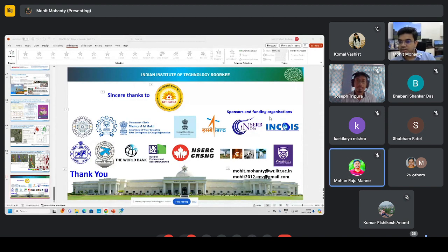Thank you, sir. There's another question by Divyashni Pandey: what are the different calibration parameters for urban flooding? For urban flooding, or for riverine flooding also, the first parameter is the Manning's roughness. Whenever we create an urban flood model setup, we also have to create a network of the man-made drainage systems, so we have to take care of what the optimum Manning's roughness coefficient should be. Similarly, for a riverine catchment, the Manning's roughness is more associated with the river channel bed form, so we also have to tune that Manning's n.